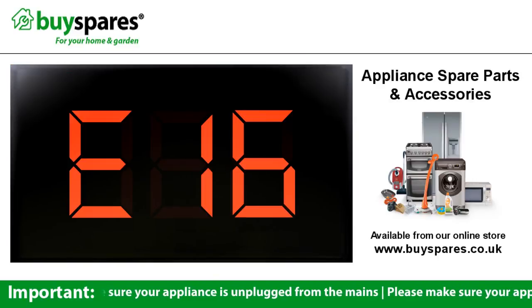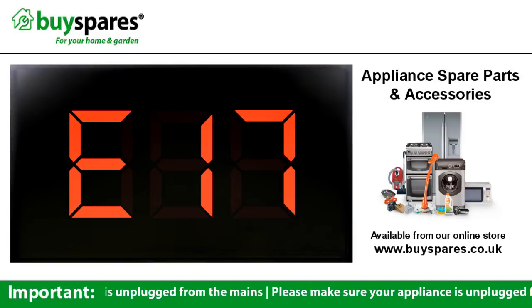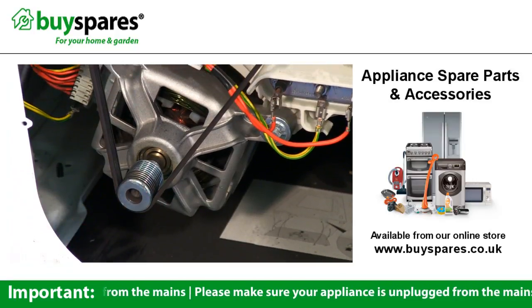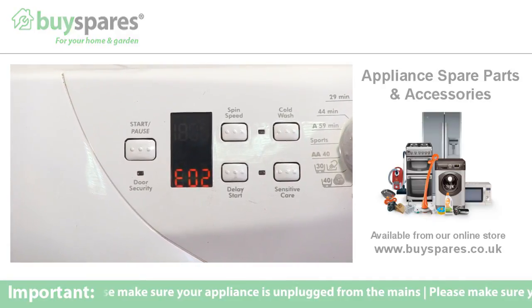E16 error suggests a heater insulation problem. This can cause tripping of your fuse box or other random cycle errors. E17 error suggests a no tacho signal that can be due to the motor not turning. E18 error suggests a faulty PCB. Remember to use these errors as a guide to the area of the problem.